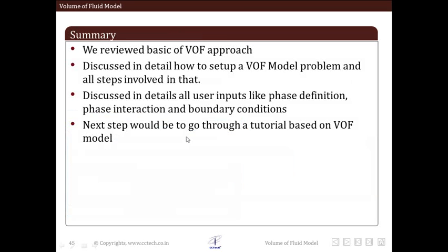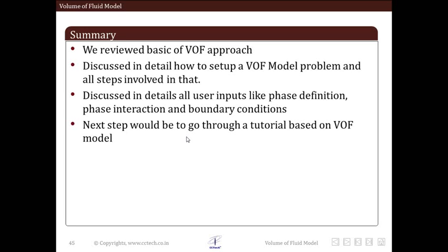So we are ending this lecture here with a summary of what all we studied within this lecture. Initially we reviewed basics of the VOF model. After that we discussed in detail how to set up the VOF model within the CFD software Fluent. We studied all the steps one by one. After that we discussed in detail all the user inputs that are required to set up a VOF model. We discussed how to set up phase definitions. We discussed how to define all the parameters that are related to phase interactions. We discussed the implicit and explicit schemes as well as wall adhesion and surface tension inputs. At the end, we also discussed boundary conditions.